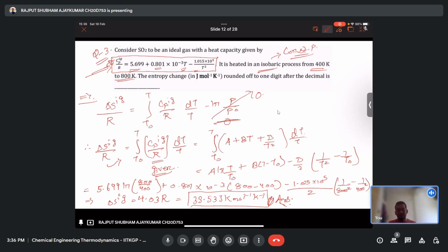Like what I did, I remembered what entropy is, what this equation is, and how to arrive at that equation, and then I formulated it. There are different temperature and pressure given. I will integrate the equation to different limits of T1 and T2 and P1 and P2. Then I write at this point, and now the process is isobaric. That means the pressure is constant. So I don't need to go further. I will just cancel this term and simplify. Now since specific heat has been given to us, I will take it directly into this equation.